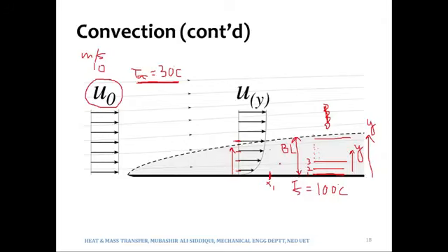So a molten metal flowing over a surface would have much higher thermal conductivities, in the range of 200, 300 or 400, and those values are much higher compared to the conductivities of air. So they have the ability to conduct heat, and they would be able to take away more energy from the heated surface.